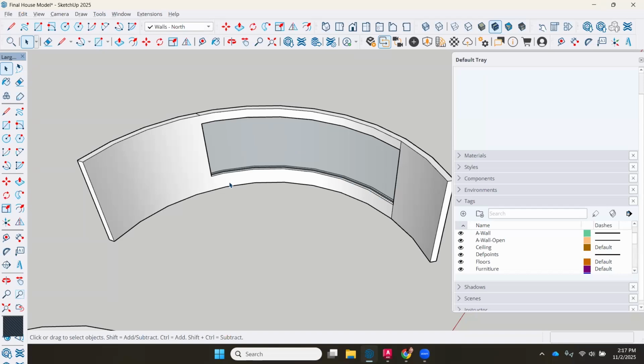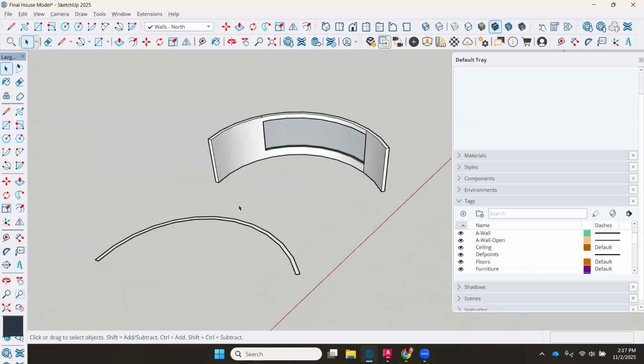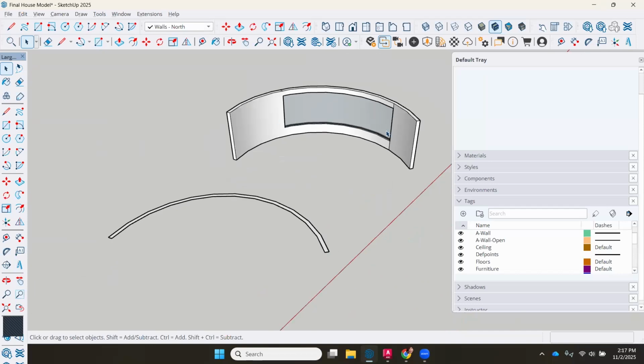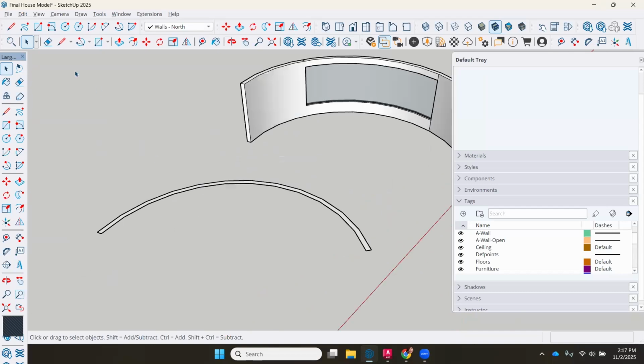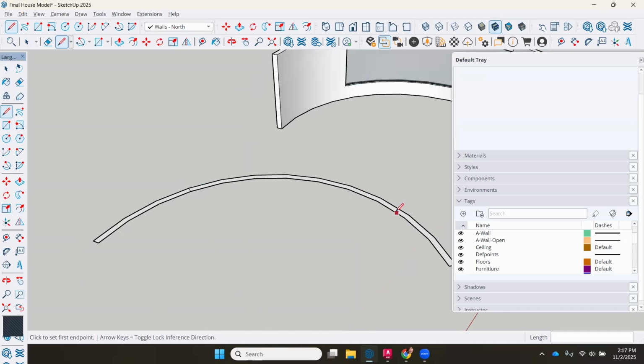It's really hard to get that precision in SketchUp, because then when we take it into Enscape, there's going to be a lot of sunlight and other things bleeding through the cracks of that way to build it. So here's a sort of shortcut, but also a way to have this be more locked up in your model so you don't have sunlight pouring through in weird spots. I'm going to rough it in, but if you're going to have a curved wall like this, here's maybe the start of one edge of the window, here's maybe the other one right there.